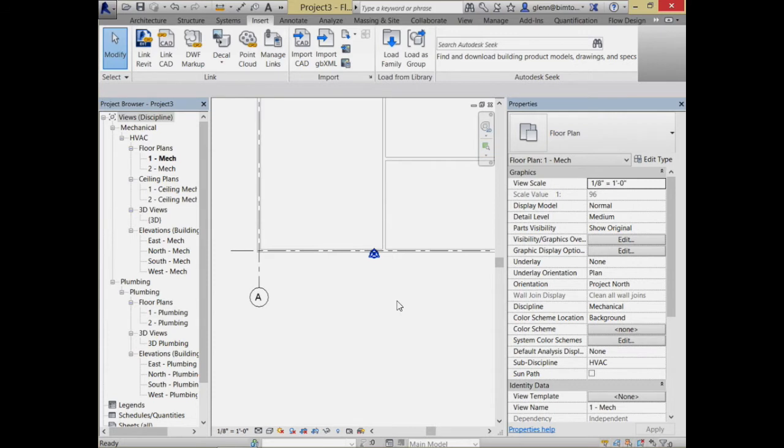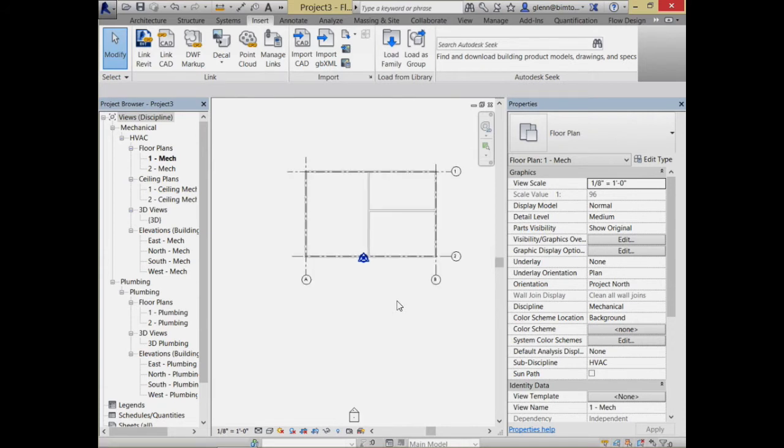Okay, that little spot right there, that's actually the origin. So one thing to check is really, hey, in both of my files, does that appear to be in the same place? If it is, super. If it's not, not so good. If you happen to link files incorrectly once, you can go ahead and remove the link and relink them again. But if you've already done a lot of work in a file that's linked not to origin, we're going to tell you how to go through and fix that, how to realign the file. Invariably that always happens to someone.